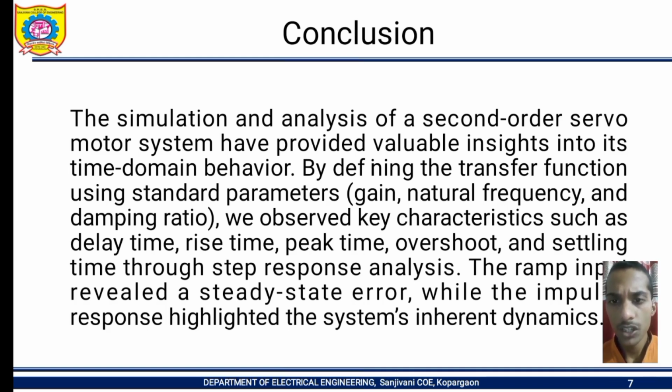Conclusion. The simulation analysis of a second order servo motor system has provided valuable insight into its time domain behavior. By defining the transfer function using standard parameters gain, natural frequency and damping ratio, we observed the overshoot and settling time through step response analysis. The ramp input revealed a steady state error.